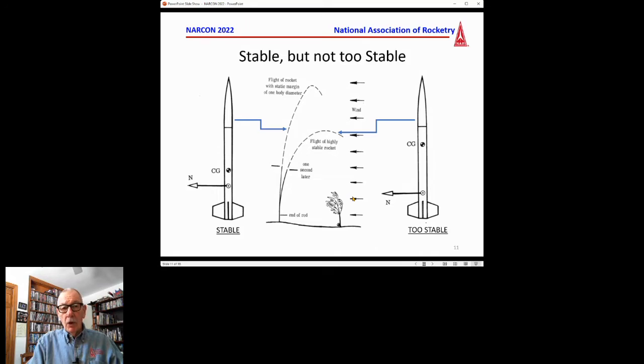The margin to see that your rocket will be stable under pretty much all circumstances. You start getting it smaller than that, and things can happen if you get, say, a wind gust that blows it into a situation where the center of pressure has moved close to or ahead of the center of gravity, then it's become unstable.